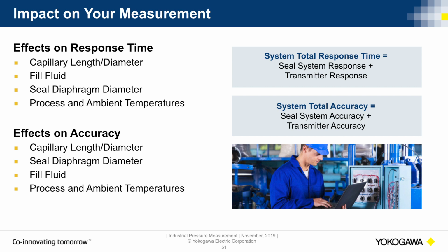Same thing on accuracy: the capillary length, the diameter of that capillary, the seal diaphragm diameter, which I'll talk about a little more, and how that affects accuracy, and again, that specific fill fluid and how much swing you're going to have in the process and ambient temperatures.